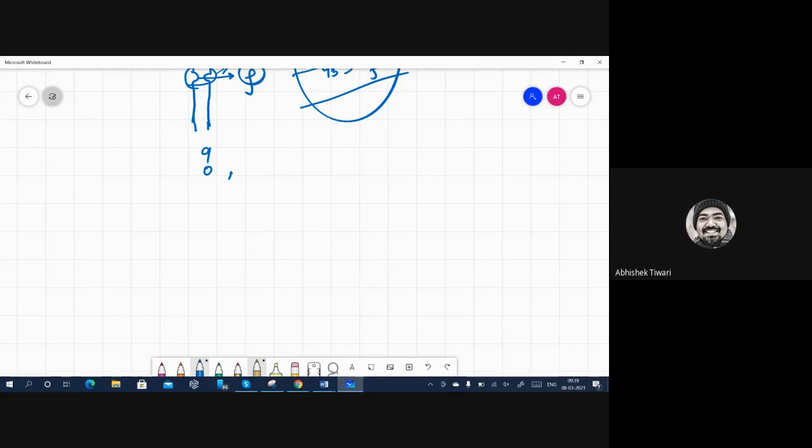Because if damage parameter is a function, or let's say I'm saying that the fracture strain is a function of strain rate or triaxiality, so I say that the fracture strain doesn't change with the triaxiality. So it remains constant, whatever is the value of triaxiality.